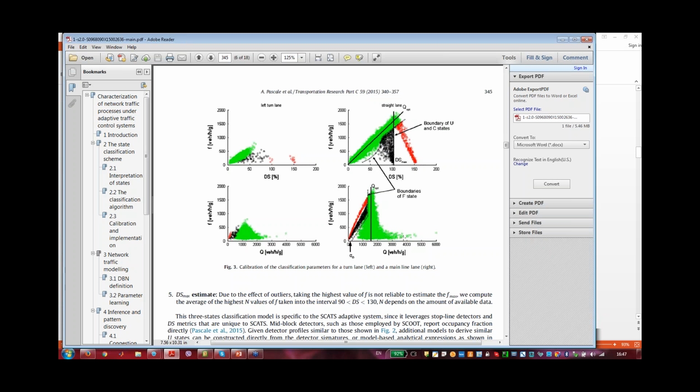Yes, this is what we have done. So first of all, we have estimated the expected service rate, and then we have estimated how this service rate can change, so the standard deviation, and then we have put a threshold on the standard deviation. Then regarding the second question, how SCATS computes the degree of saturation is quite tricky. There are a lot of different parameters that are calibrated underneath this number. So what happens in the congested state and the black one?